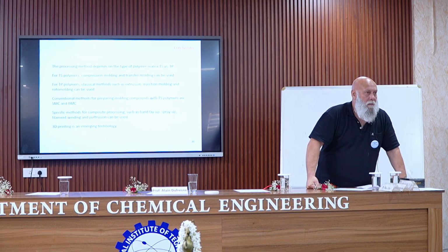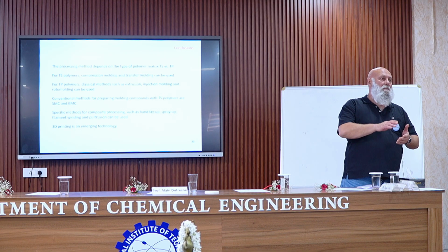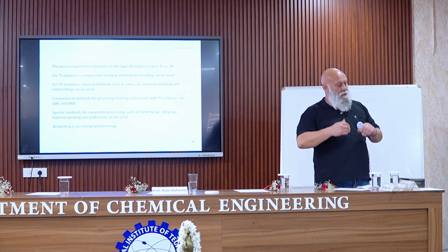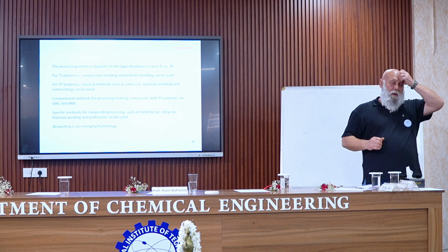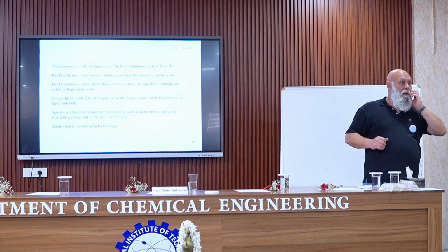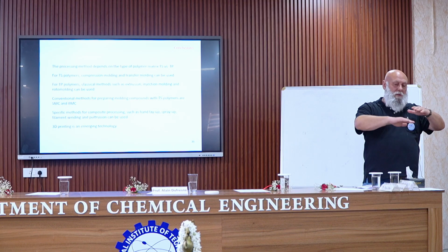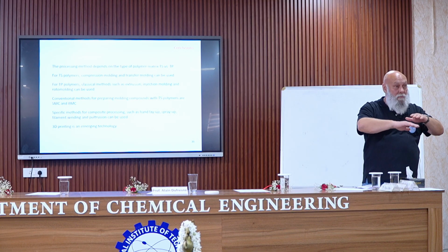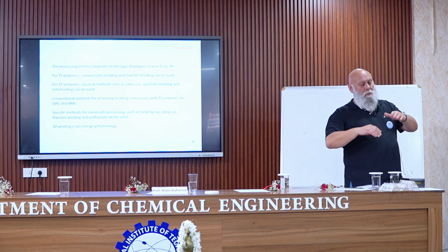In some cases, it can be hot pressed, but it depends on the miscibility between the two layers. Another option can be welding, which consists in locally heating the two layers by the movement of a metallic plate, for example. Ultrasound can also be used, and then you press the two materials, which are only locally melted.